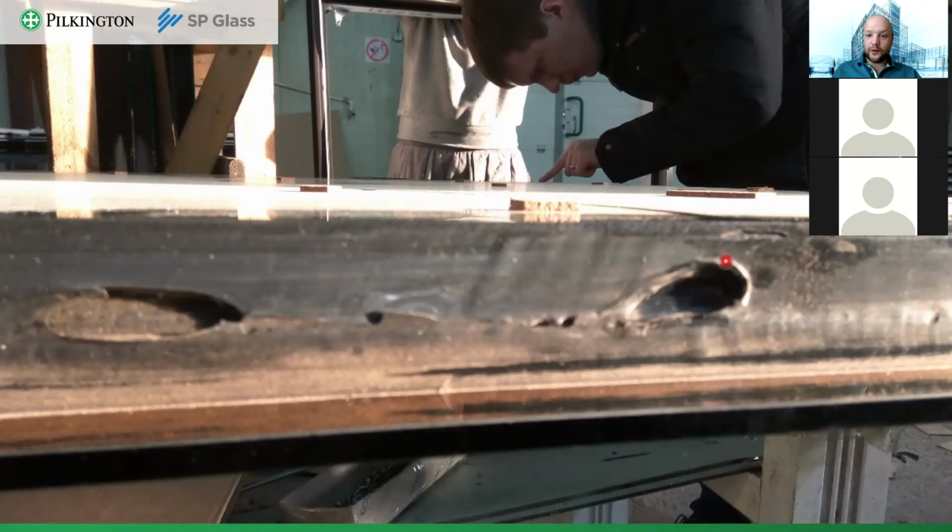At first, the holding capacity of the secondary sealant here is severely compromised. And it's even worse in colder climates because these gaps can be filled with water. When exposed to negative temperatures, the water can freeze and tear it apart from inside. This is a critical one.